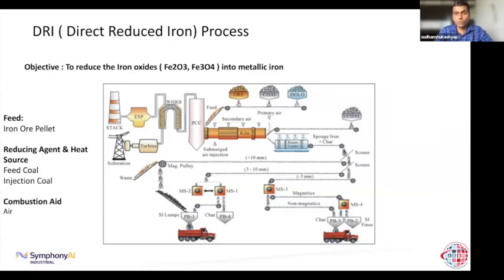And of course, if you want to do combustion here and raise the temperature, then you need some combustion air as well, and that is done by air. Air is being supplied from the rear end, that is the primary air, through a fan. And there are air tubes on the kiln which supply the secondary air as well, as you could see here.